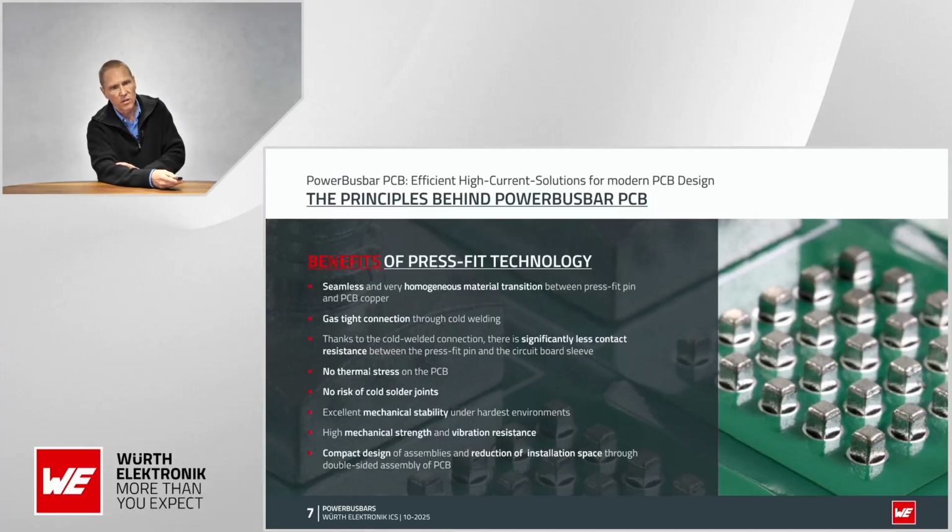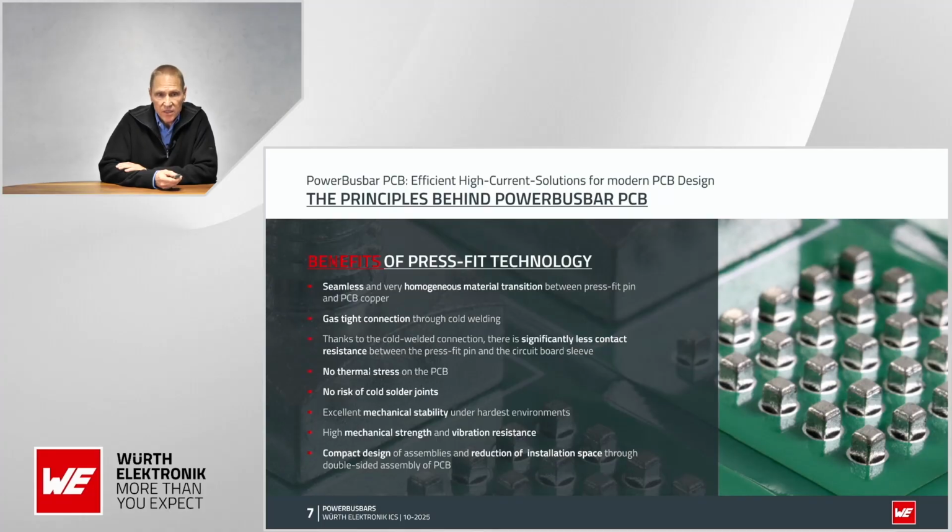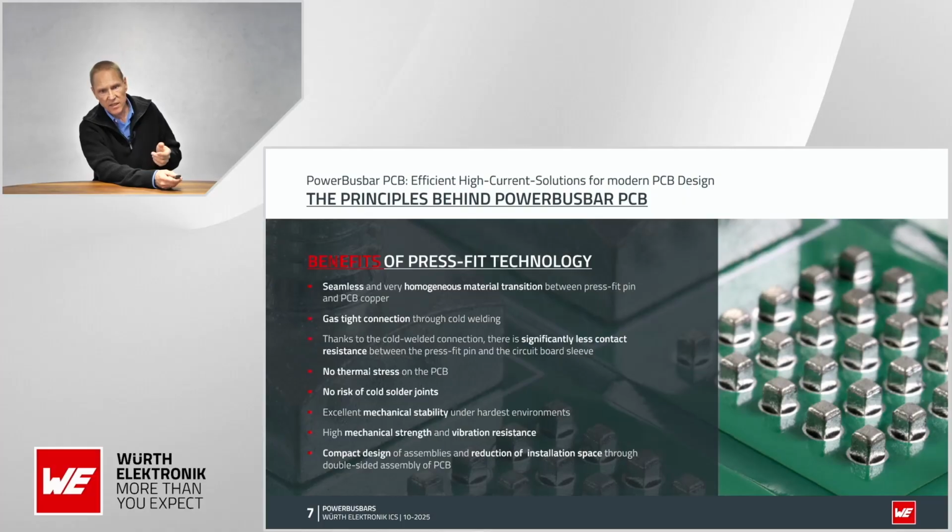But let us have a look at the press fit technology itself. The press fit technology creates a seamless and very homogeneous material transmission between the press fit pin and the PCB copper. This connection is a gas-tight connection through a cold welding process. And thanks to the cold welding process, we have a significantly lower contact resistance between the press fit pin and the copper sleeve in the PCB.